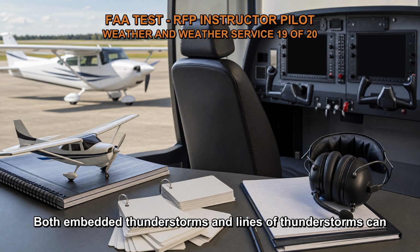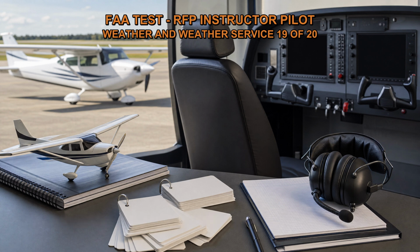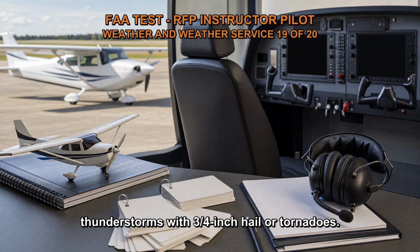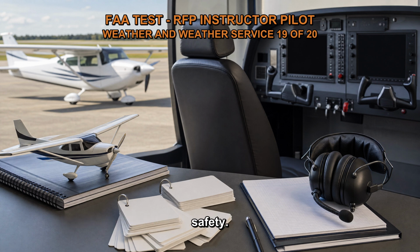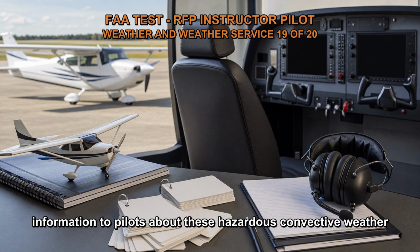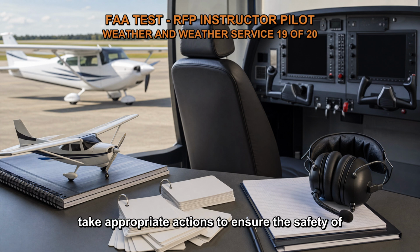Both embedded thunderstorms and lines of thunderstorms can pose significant hazards to aviation due to the potential for severe turbulence, strong winds, heavy precipitation, and other associated phenomena. In addition, convective SIGMETs also include information about thunderstorms with 3/4 inch hail or tornadoes. Hail of this size can cause damage to aircraft, and tornadoes are powerful rotating columns of air that pose a severe threat to aviation safety. By issuing convective SIGMETs, meteorological authorities provide timely information to pilots about these hazardous convective weather conditions. This allows pilots to make informed decisions and take appropriate actions to ensure the safety of their flights.